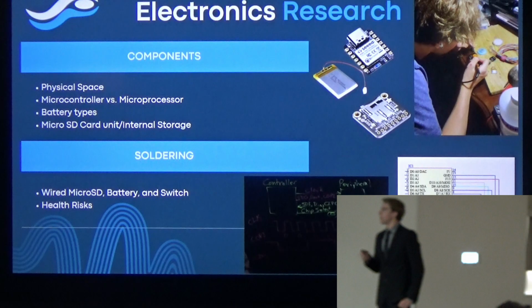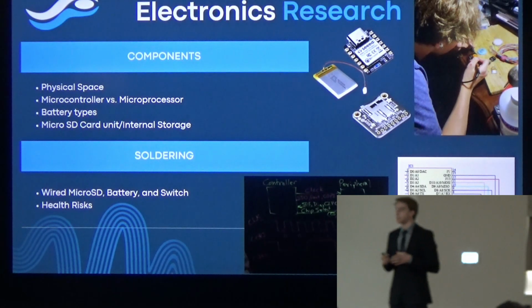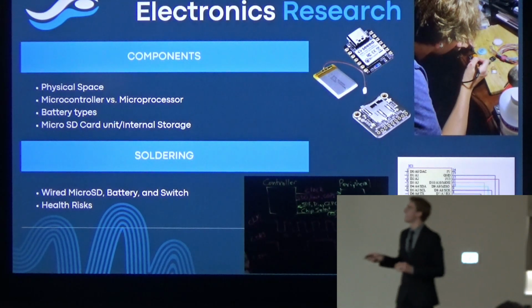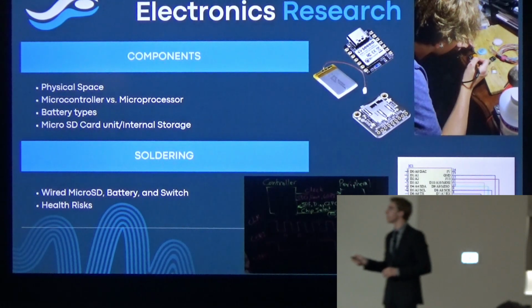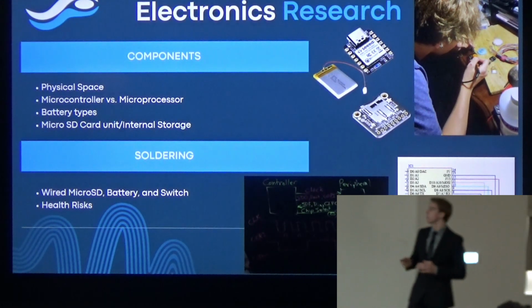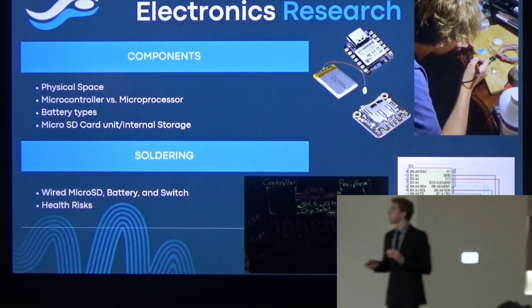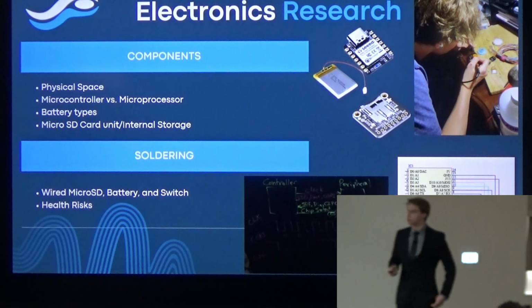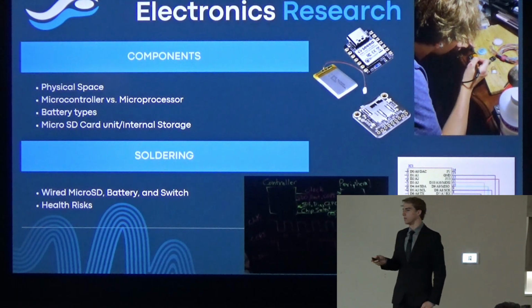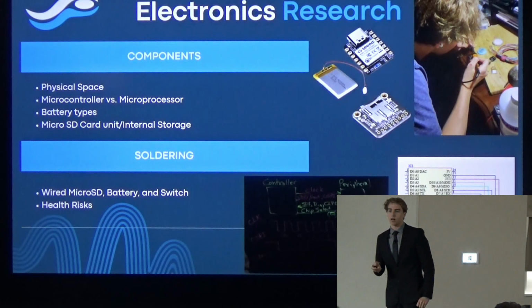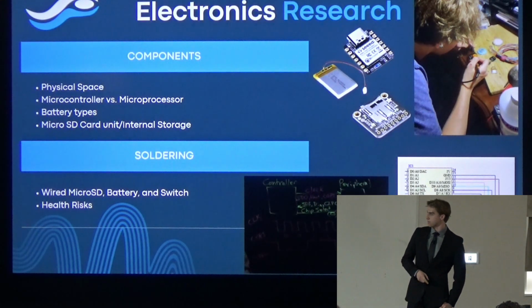Additionally, I worked on battery types, so I needed this to be very compact. I ended up using a LiPo battery. The other option I had was a coin cell, but the LiPo battery actually had built-in integration with my microcontroller. Additionally, it is rechargeable, so it cut down on the cost of the project.